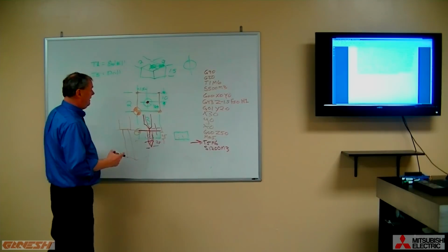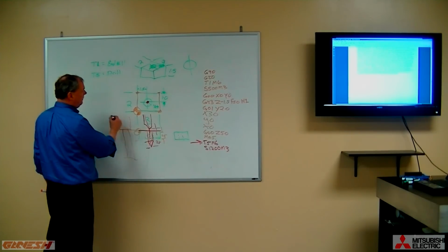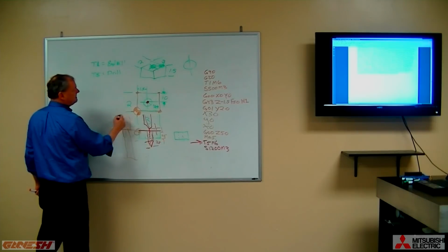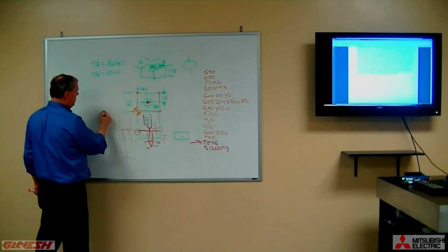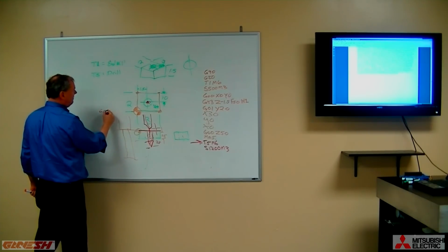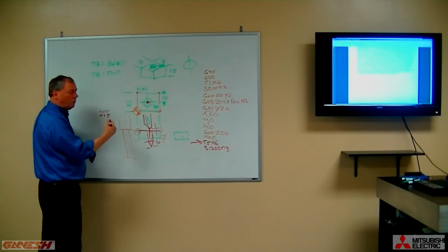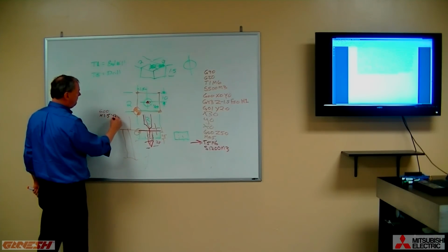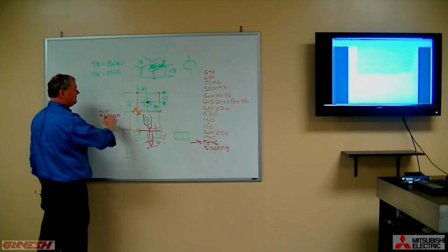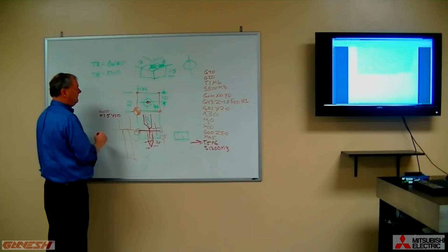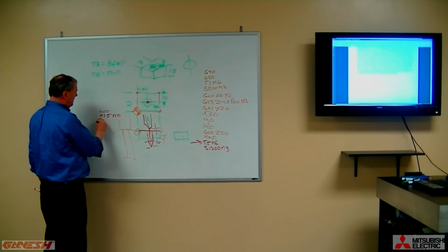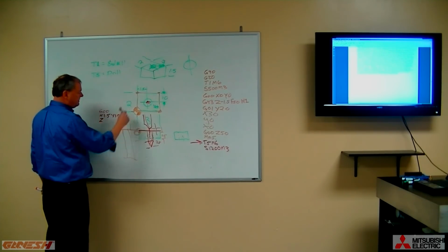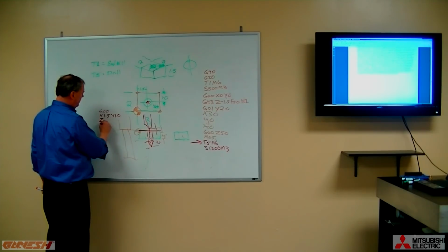We can do it long-handed. We could do the equivalent. We could say, for instance, we now want to position over the hole. I could say G00, X1.5, Y1.0, right? We can go G00, get us right to that point. Then I can say Z, in other words, rapid it down to 0.1 over the part.